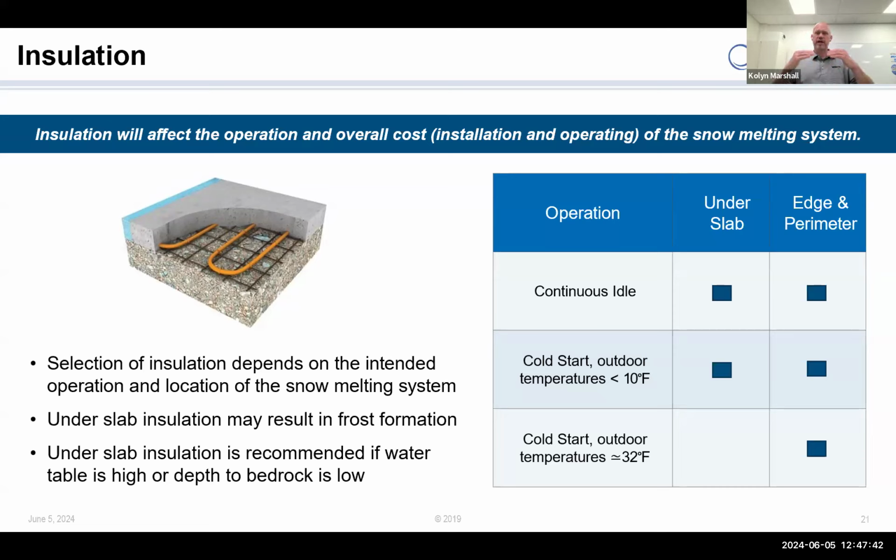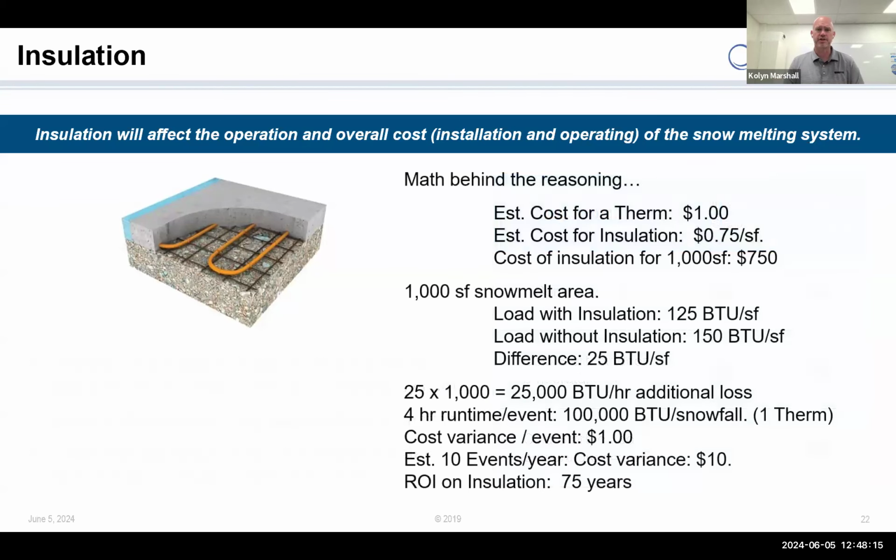If that compressive area gets too big and that void gets too big, then over time, repeated vehicular loading on that point will cause the concrete to crack. You create stress risers, and it'll just crack. So you have to account for that and make sure that you choose the right insulation. Well, 2-inch insulation costs way more than a 1-inch insulation board does. So there's a cost factor, a hard cost factor associated with the insulation itself.